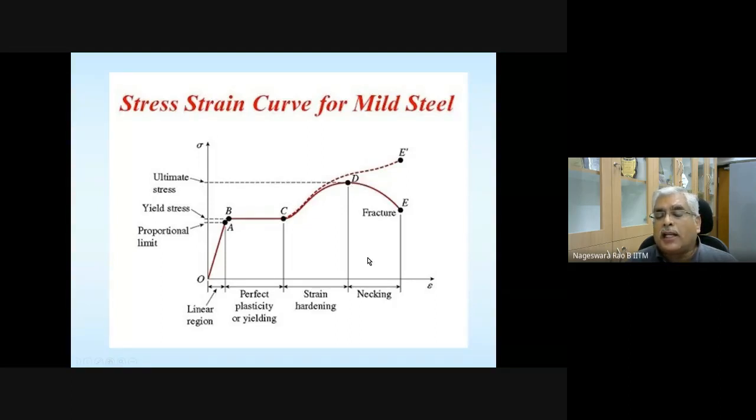In this region, necking is going to happen. If you take a tensile test specimen and do the testing, when the stress is in this region, you will observe necking and reduction in the cross sectional area. When necking happens, the cross section of the specimen reduces. That's why the curve is splitting up. Which cross sectional area you are using to calculate the stress, that is where the difference between engineering stress and true stress comes from.